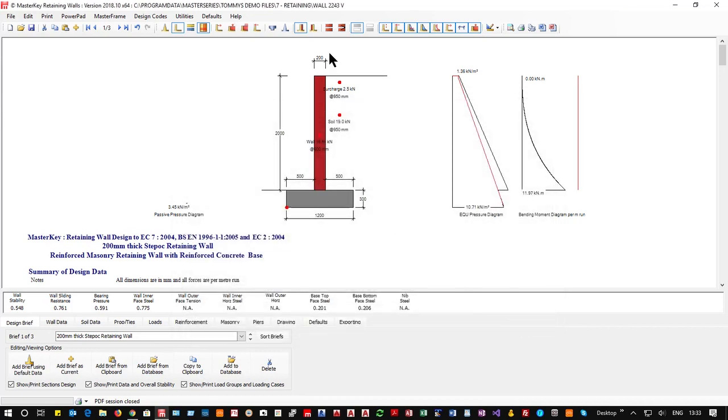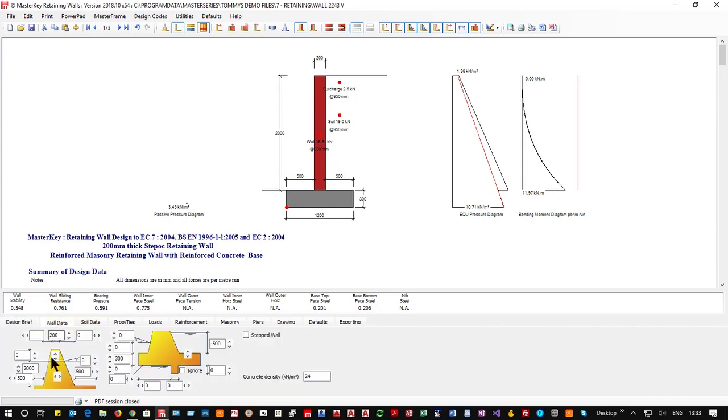So I'm now using my own version, at which point I can see which of the three walls I want, and I can then come along and delete the wall I don't want. So I have all the data set up here for me, ready to go. I can turn around and say, well, actually the wall is going to be with a 12-degree slope, and it's going to have the water table at, well, you probably don't want the water table on a masonry wall other than down below, so we'll not worry with that.